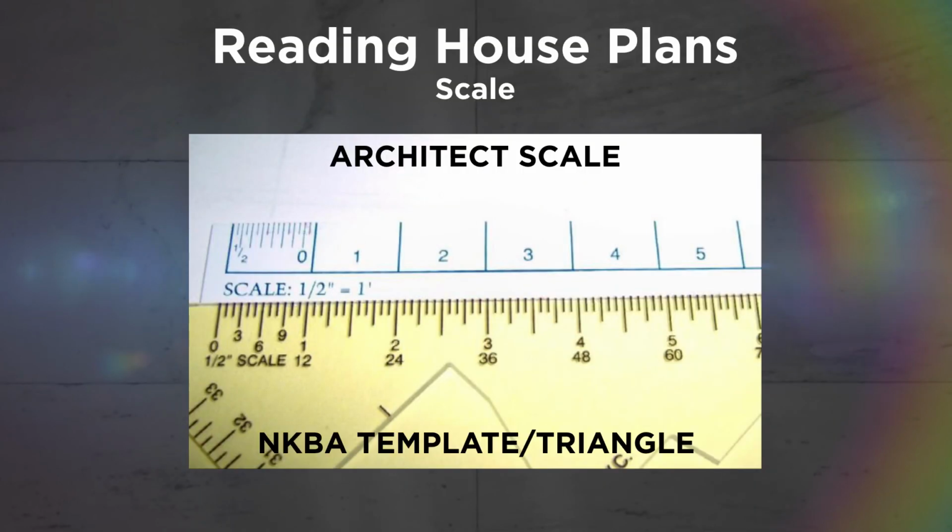But as kitchen and bath designers, we work with single rooms, and because of the detail required for a completely documented kitchen and bath project, we use a bit larger scale, or the scale of 1/2 inch equals 1 foot. And we work in inches only, not feet and inches.